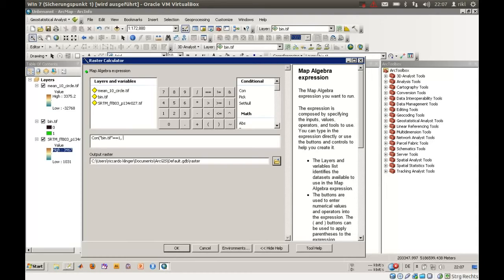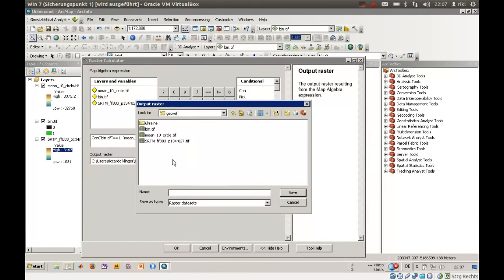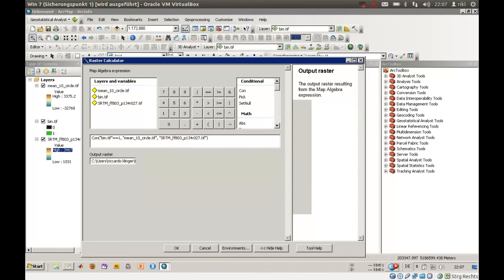Because there was no data available. On those pixels, we will use the information from the mean file. Else, we will use the information of the original data. We will store that information in a third one, SRTM_filled_with_means.tiff.